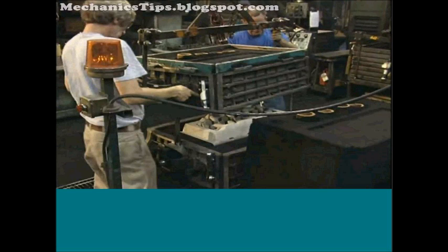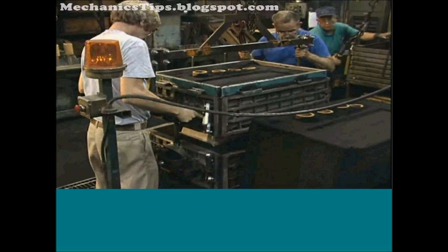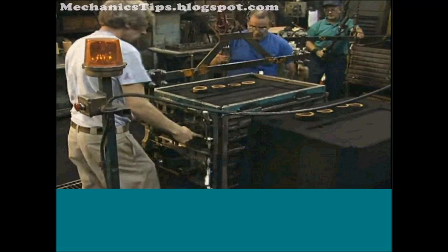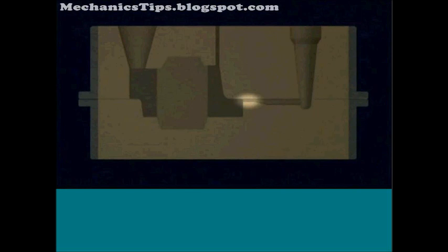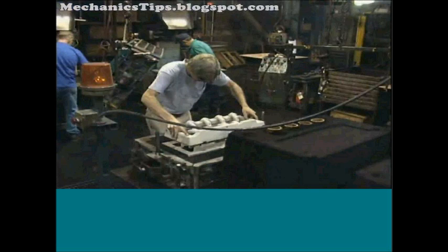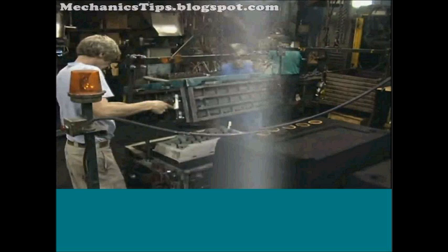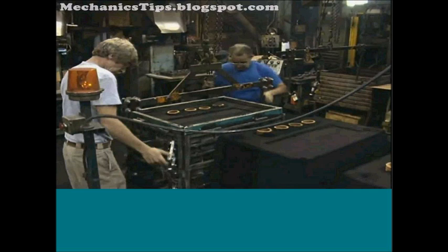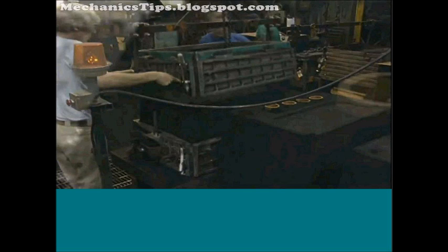The mold includes one or more risers, venting provisions, and a system for transferring the molten metal to the mold cavity. This system includes a pouring basin, sprue, runner system, and one or more gates. Once the sand has been compacted, the pattern and mold half are separated, and any loose sand is blown away. Cores, if required, are inserted into the mold. Once they are set, the mold is closed by aligning the cope and drag. The mold is then transferred to the pouring station.